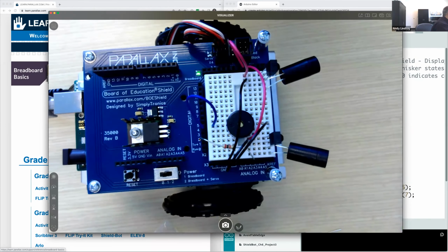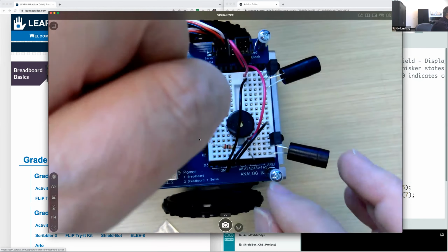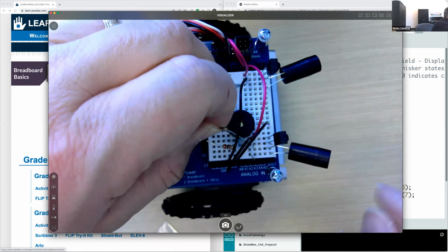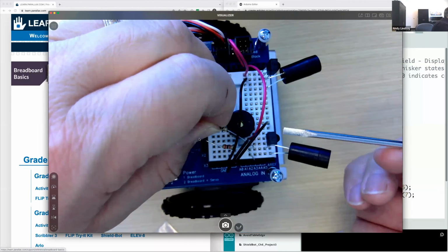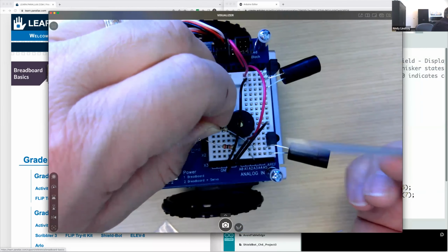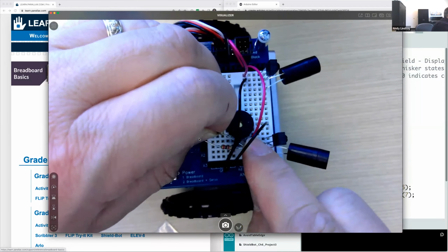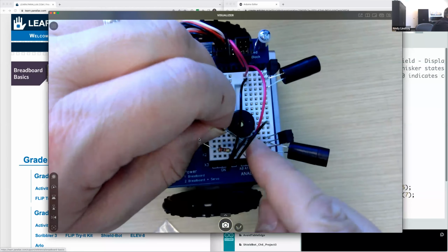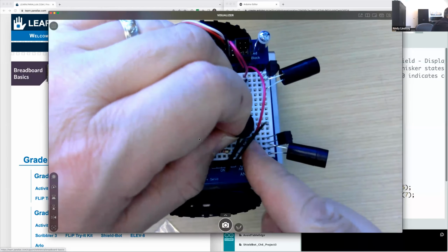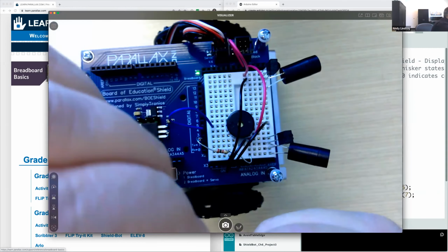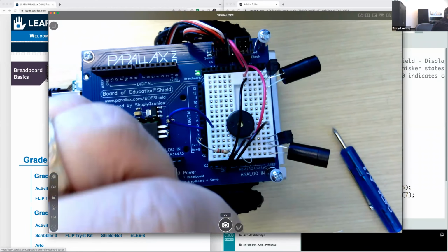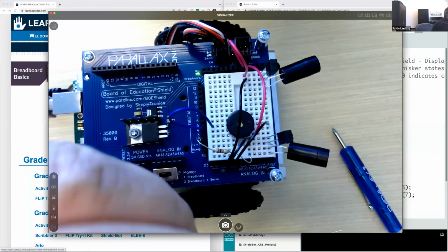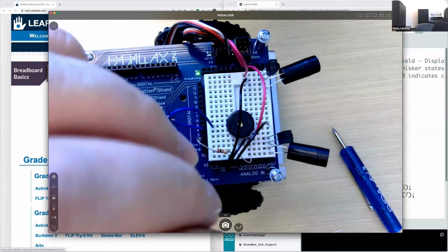Next up, a red, red, brown resistor, that's 220 ohms, needs to go to the bottom of the 3 pins of the infrared receiver. And make sure that everything sinks in by 1/4 of an inch. I'm bending the lead on this instead of getting it to sink in.